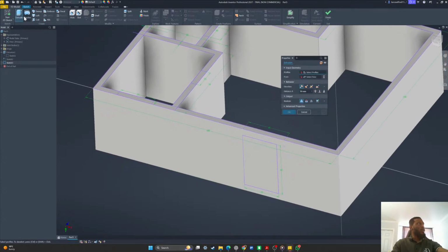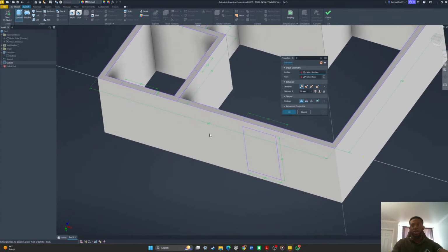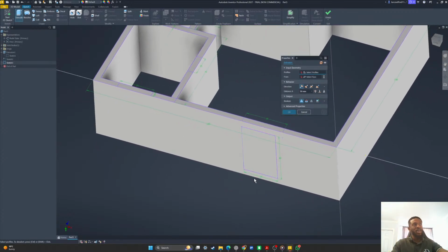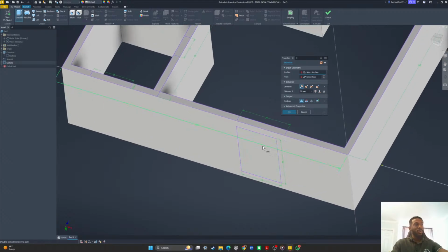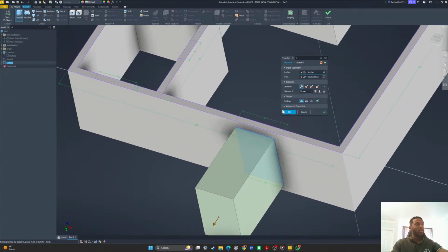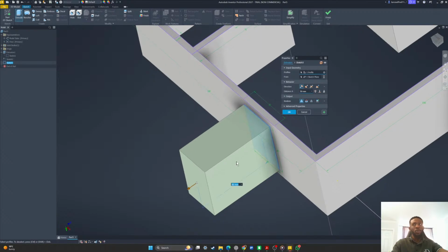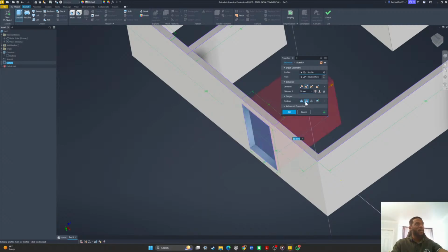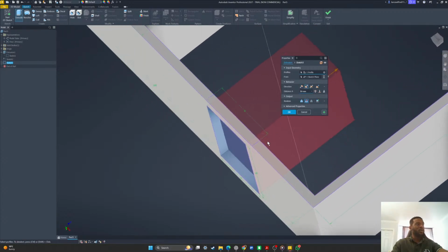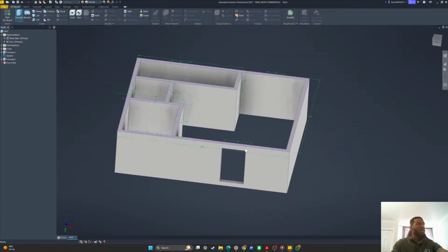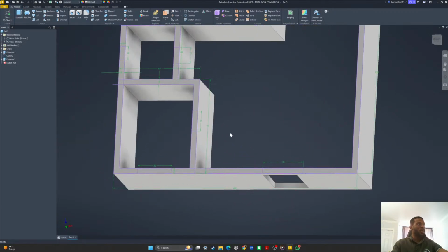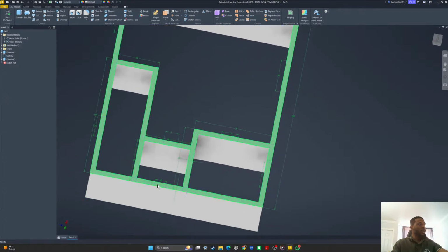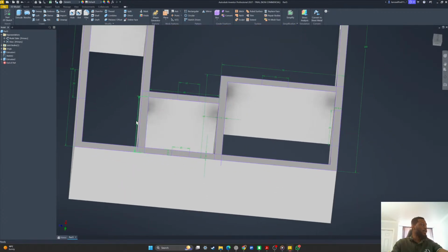You know, when we clicked on the extrude the last time, we were adding material, but there's another function to this. It can also take off material. So when I click on this box here, it comes out, but that's not what we want. I want to take off this material. So I'll click on this, and this is what we call cut. So it cuts the material, and then that's where our door is going to go right there. So we're going to make this little window next.